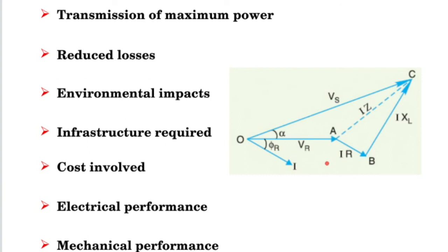No, it's not possible, because of the reactive power. If you have a generator and a single transmission line connected to it, it's going to draw some reactive power. The generators need to supply the reactive power, so the generator power factor will immediately become lagging as well, because the transmission lines cannot operate unless they draw some reactive power.